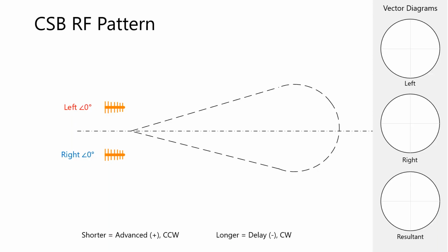Okay, we're finally ready to analyze the development of the localizer RF pattern in greater detail using vector line analysis. For simplicity, we will consider just one pair of antennas from a localizer antenna array. This example does not include modulation, only the RF pattern developed. This pattern results with or without modulation. Later lessons will consider the effects of modulation, but for now, just focus on the pattern development.